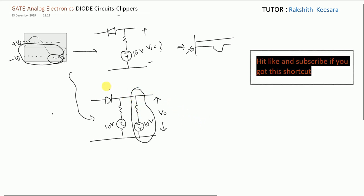So what will be the output voltage? The voltage below plus 10 is completely clipped off and the voltage below minus 10 is also clipped off. So this is just given to confuse you. So this will be the output voltage. This is the plus 10 volt.